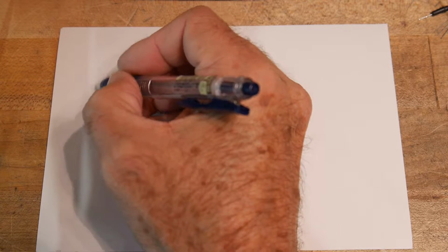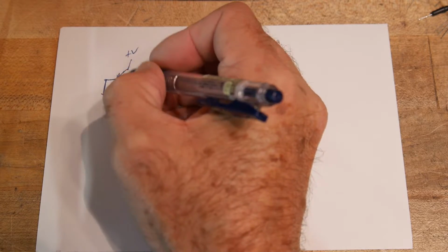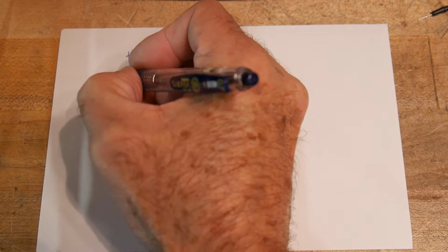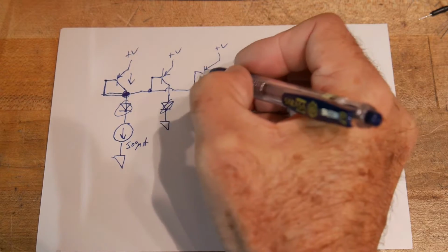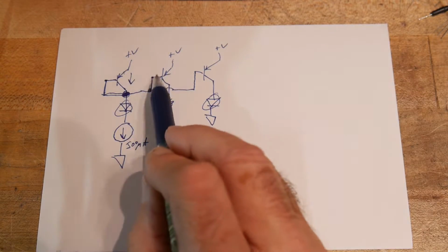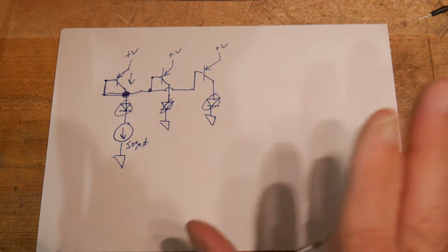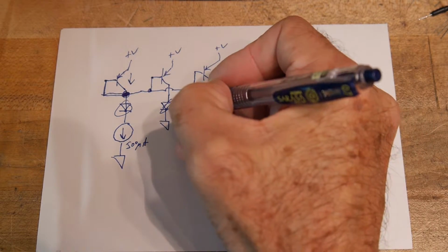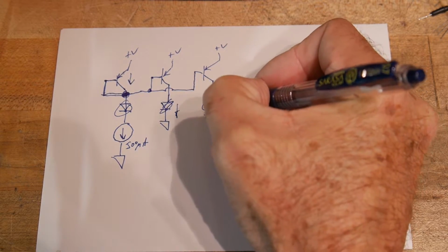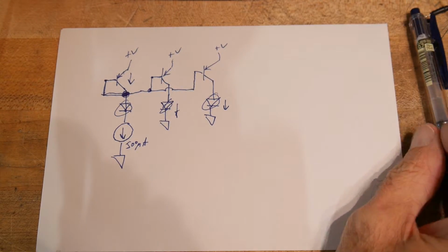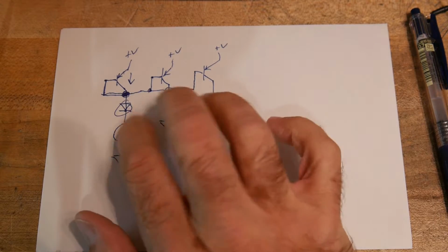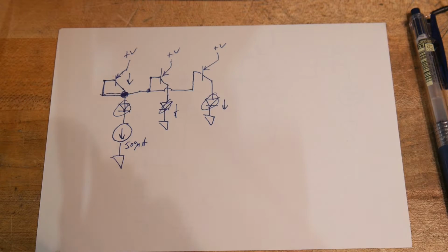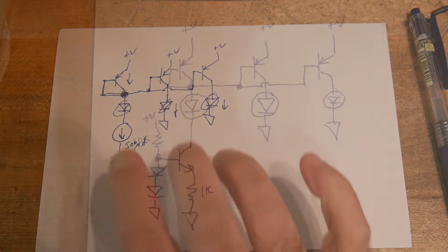But that sets a condition in this transistor, and that condition is this 500 microamp condition. So it kind of sets the base voltage. And if we set the base voltage to these other transistors, and if these transistors all have the same characteristics, then the conditions of these two transistors will also be such that you'll get current in these two transistors, LEDs as well. And these three LEDs should light up to 500 microamps. So let's build that circuit.